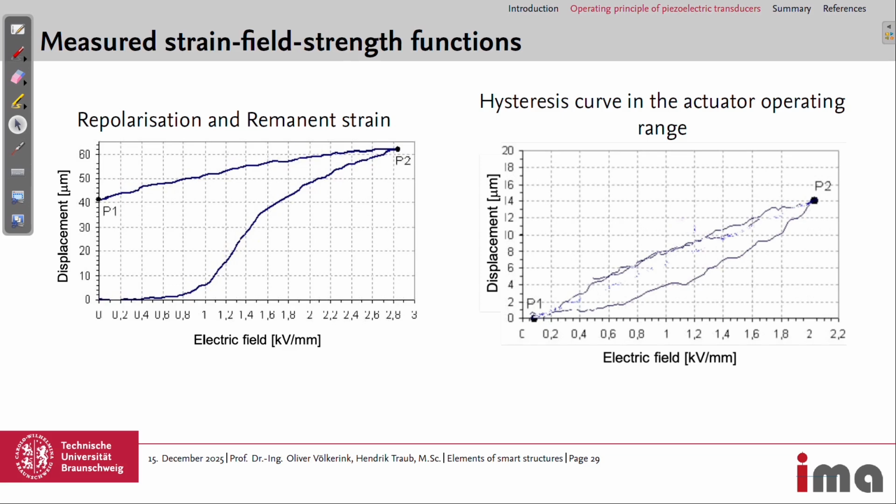You have mentioned that we require at least 2 kilovolts per mm for the polarization. Doesn't it depend upon the thickness of the material also? Yeah, sure. If the electrodes are further away, then you need a higher voltage. This quantity is specific to the thickness.